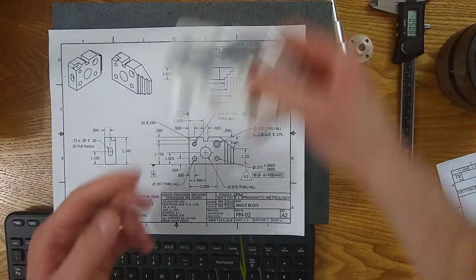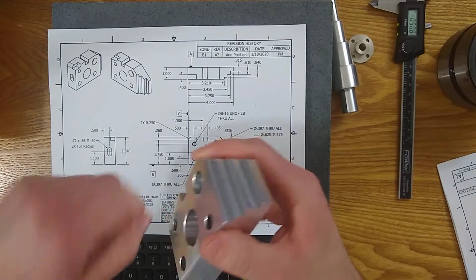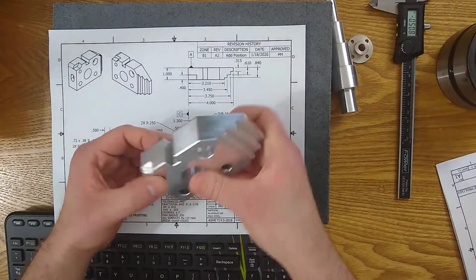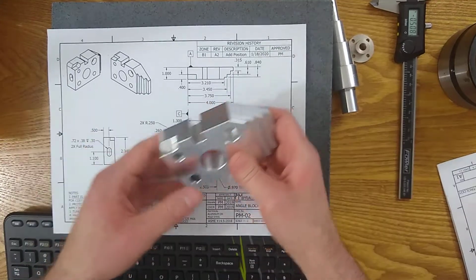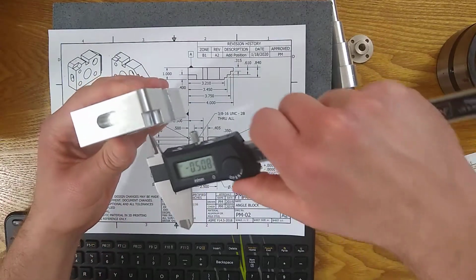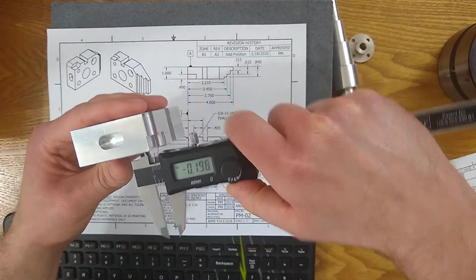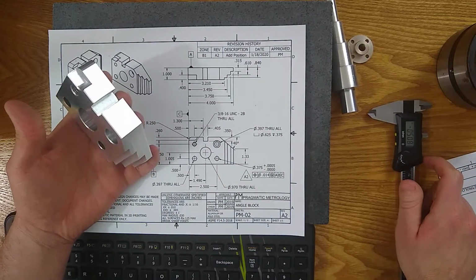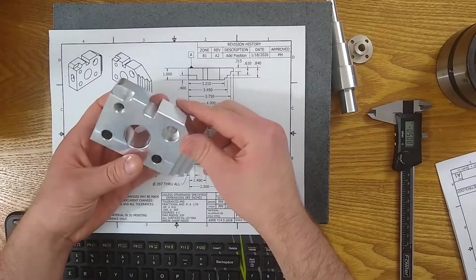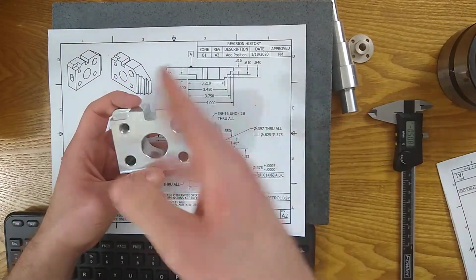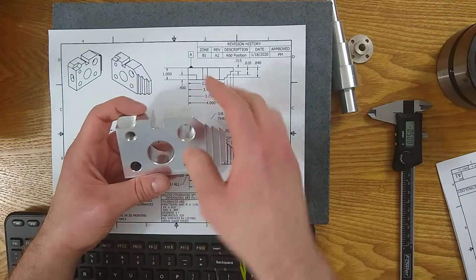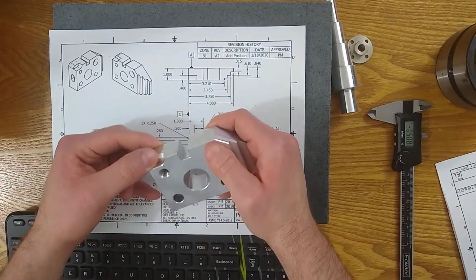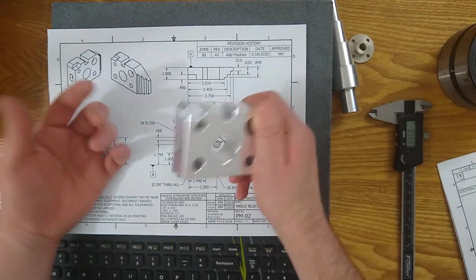For tapped holes, this part's got a tapped hole. You're going to check it with a go and a no-go gauge, which we have videos about for checking holes as well as for go, no-go gauging. The minor diameter is optional. The minor diameter is going to be the through hole diameter. Some places are going to ask you to check it. Other places think checking it on every hole is excessive. It won't be stated on the print most of the time, the through diameter for the thread. So most of the time, checking with the go, no-go thread diameter, pitch diameter is going to be satisfactory.